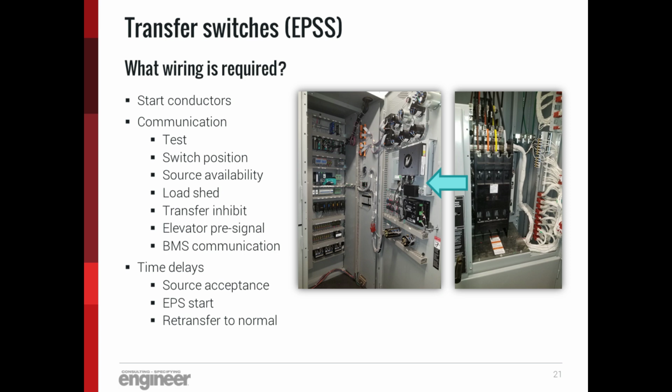With respect to annunciation locally and annunciation outside the facility, unfortunately, for those who basically fall under the CMS requirements at this point, that would be the 2012 codes, which have invoked the 2010 edition of 110. The 2010 edition does not presently allow this sort of transmission, this sort of connectivity, for the emergency power supply section.